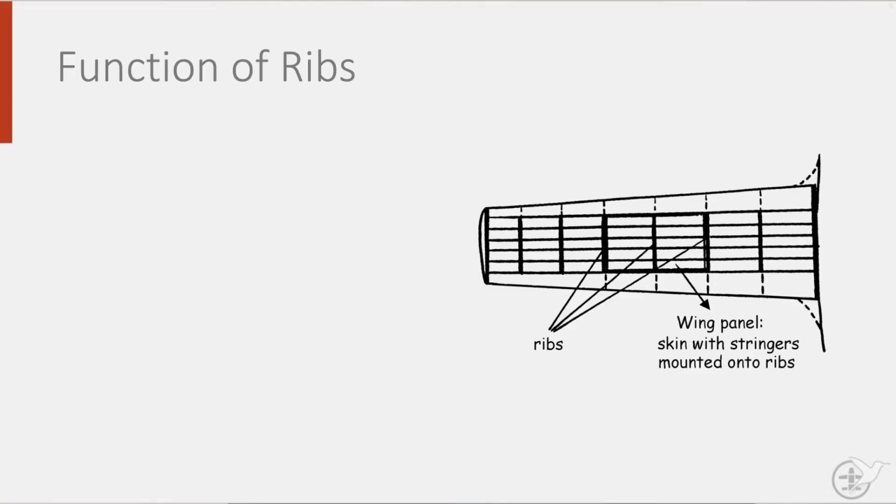Today, we will look at an important structural element in wings, the rib. Ribs have an important function in wing design. They ensure that the wing maintains the aerodynamic shape or profile so that lift is generated as designed by the aerodynamicist. As an aerodynamic profile is defined in flight direction, ribs are often placed in flight direction also, even though sometimes it is easier from a manufacturing point of view to place them perpendicular to the spars.